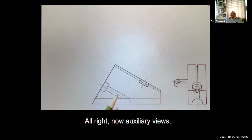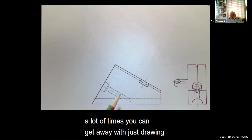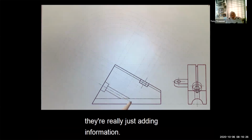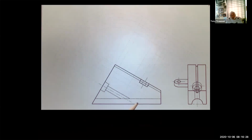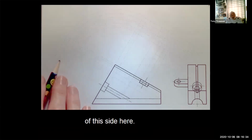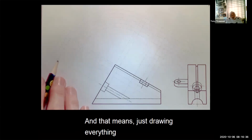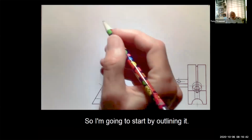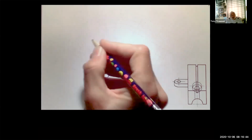All right, now auxiliary views, a lot of times you can get away with just drawing a partial view because they're really just adding information. So let's start by drawing a partial auxiliary view of this side here. And that means just drawing everything that's on the surface of this left side here. So I'm going to start by outlining it.